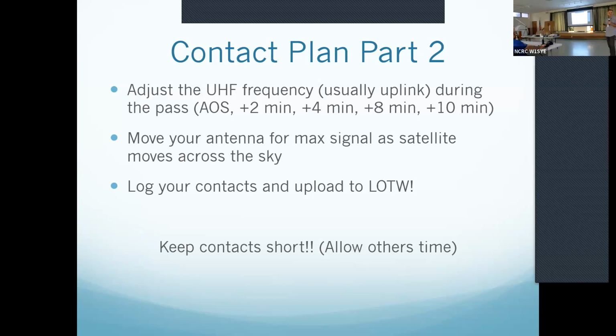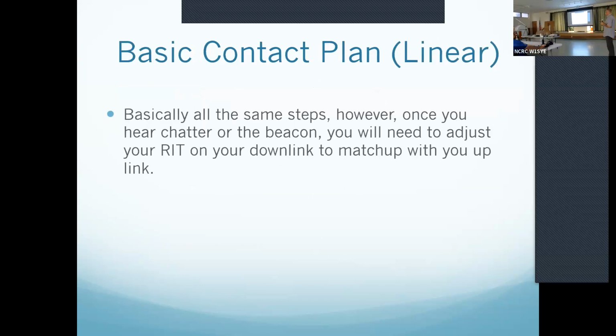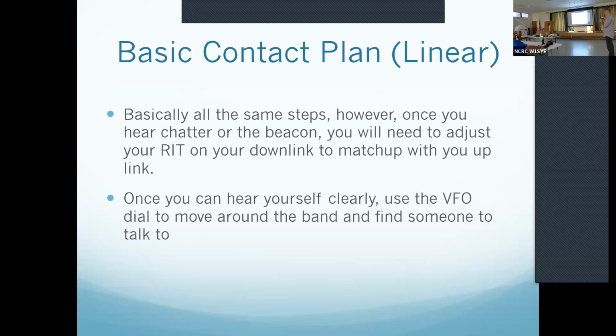All right, next one, it should be the linear one, right? Yeah. Now, the linear ones are a lot more fun because there's a lot more dial playing and messing around with the radio, because you have that huge bandwidth of 20 to 100 kilohertz. And your radio is not going to be perfect and the satellite's not going to be perfect. So when you stop talking up and you know it's coming down, you might not hear yourself right. So you have to find where you are in the band.